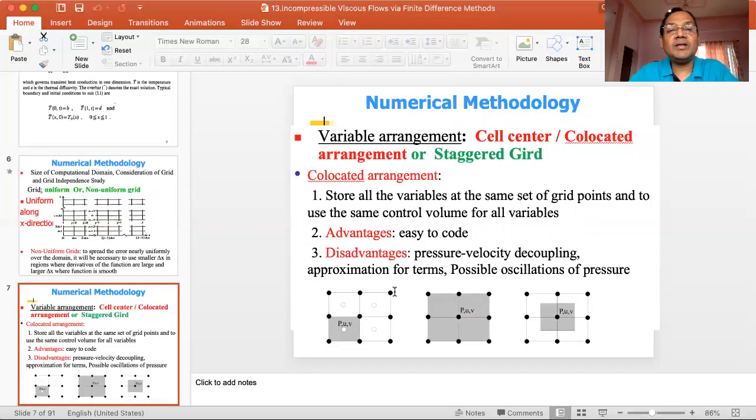In problem 3.1, 0 to 1, the space variable is one. But if you have more than one space variable, you have to define x-axis subintervals and similarly y-axis subintervals, and you will have some blocks. Those blocks are defined as control volumes.